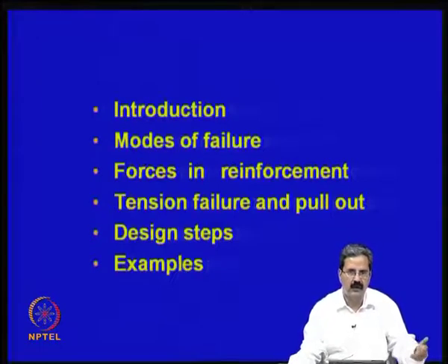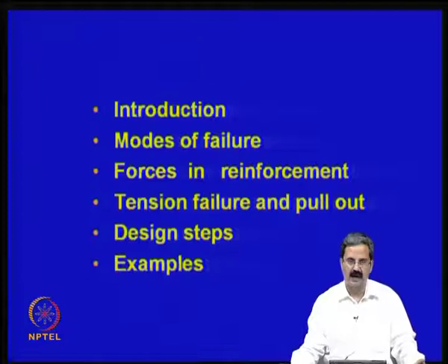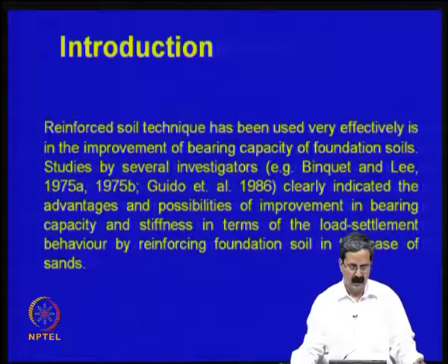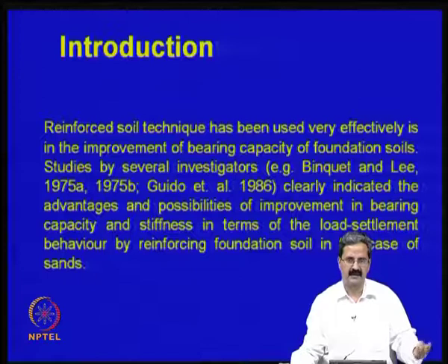So, when you want to increase the bearing capacity or reduce the settlements, you need some sort of improvement in bearing capacity. We have seen in the earlier classes that one can use bearing capacity improvement techniques such as stone columns and prefabricated vertical drains. Many techniques are possible, even additives. These are all very useful techniques to increase the bearing capacity.